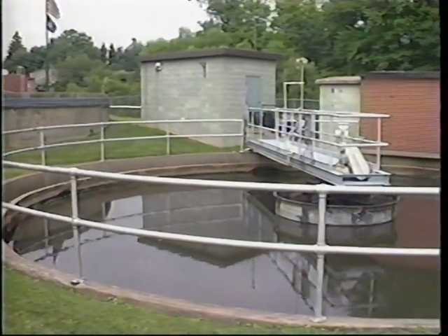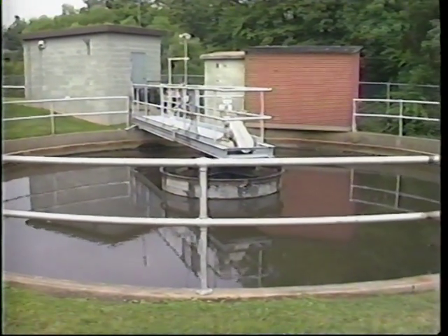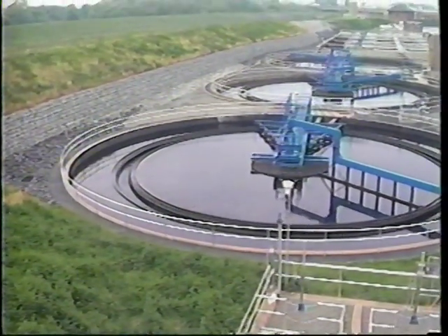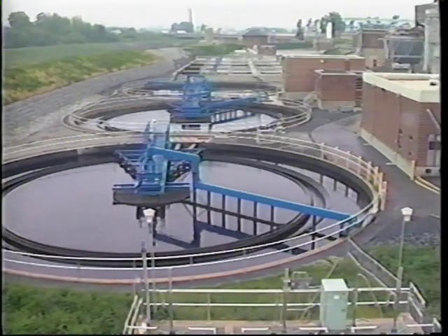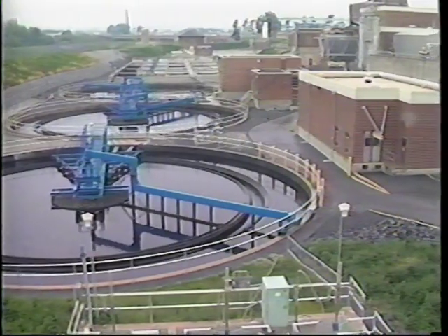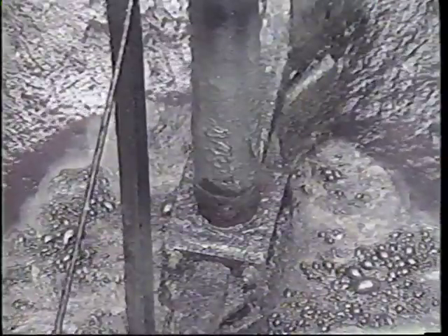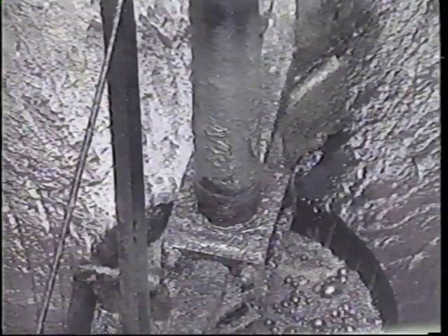Secondary clarifiers are located downstream of a biological treatment stage. In advanced facilities that have more than one biological treatment stage, an intermediate clarifier separating the two biological treatment processes may be found as well. The clarifier following the final stage of biological treatment is usually known as the final clarifier. In any event, the solids removed from a secondary clarifier are different from the solids removed in primary clarifiers. The settleable solids removed from a primary clarifier tend to be much denser than those removed from a secondary clarifier.